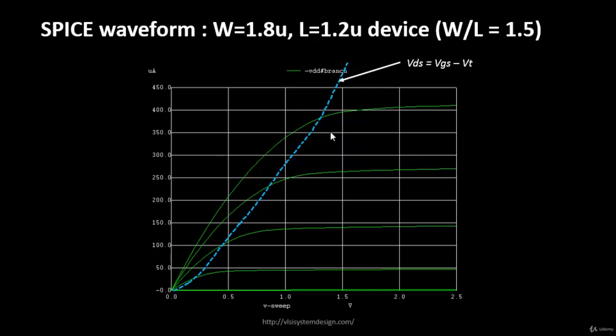So the same MOSFET has two different behaviors at two different points, and the point is this one. Before this, the device is in the resistive operation, in the linear region, and over here it's in the saturation region. We had explained the concepts behind why all this happens, so we'll revisit these equations again.